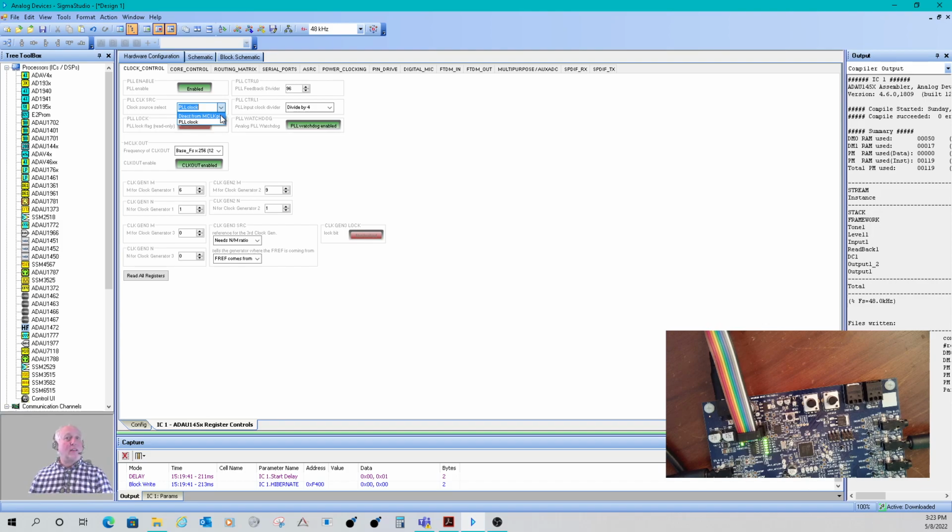So you always want to have this set to PLL clock, because it's expecting a 294 megahertz signal, and if you send it a 12 megahertz signal, guess what? The DSP is running extremely slow. So that should always be set to PLL clock. And they get 96 and 4. Now this is set up for a 12.288 megahertz oscillator. The data sheet goes into all the various frequencies and settings you can use. I won't bore you with all that here. But that sets up the basic PLL output frequency, a known rate.